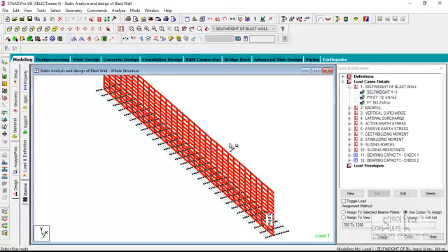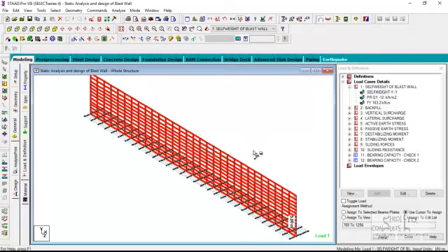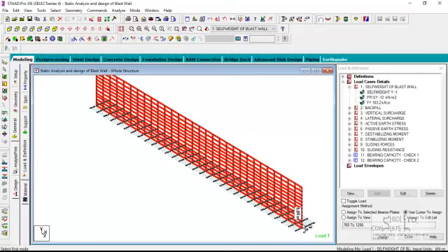Like I said, this self weight loading has increased the load by that additional modeled height of 0.5. So we need to calculate a weight corresponding to 0.5 and apply it at the centroidal location of the total weight of this, right? It counters it and gives you the total weight, assuming that you modeled a 4 meter height of wall. So the weight corresponding to 34 by the thickness of the wall by 0.5 was applied as a counterweight, so that the equivalent total weight will be the total weight of the wall, assuming a height of 4 meters.